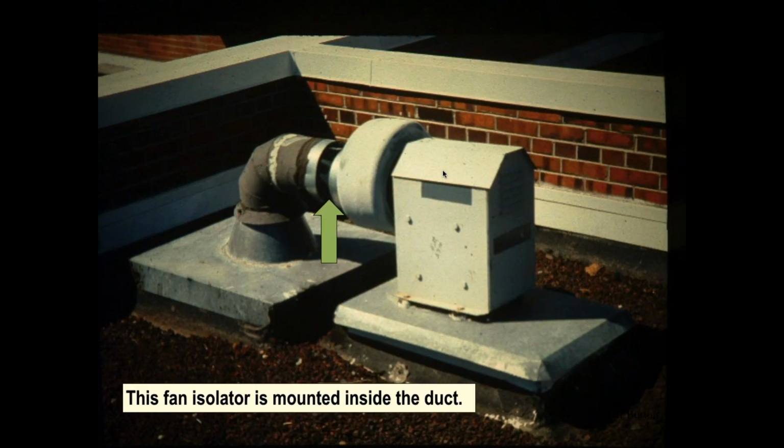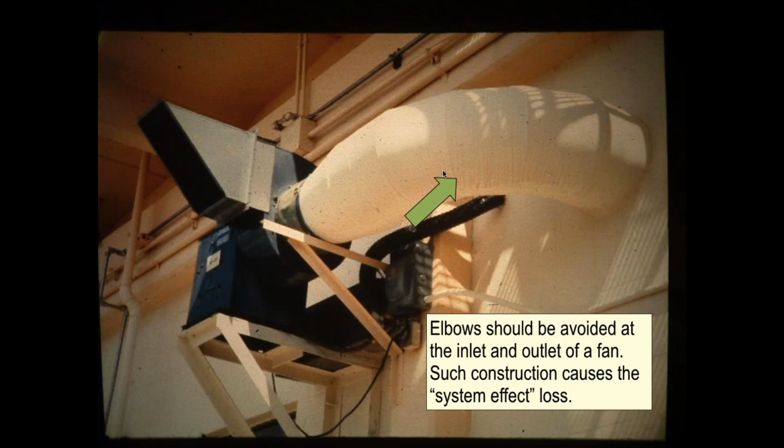So if you need to turn the fan at 3,000 revolutions per minute in order to get the flow rate that you want, the Q that you want, right? You're not going to buy a motor that's designed to turn at 500 revolutions per minute, because then you're going to have to gear it up so much that it might be difficult to get it to work properly.